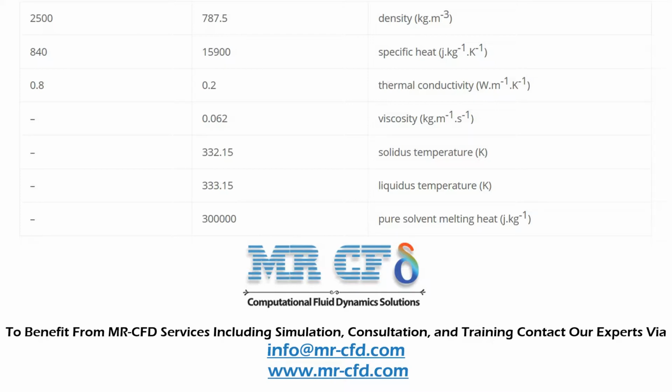To use the solidification and melting model, the maximum temperature at which only the solid phase exists, T solidus, the minimum temperature at which only the liquid phase exists, T liquidus, and the latent heat of melting in the pure solvent state must be used.